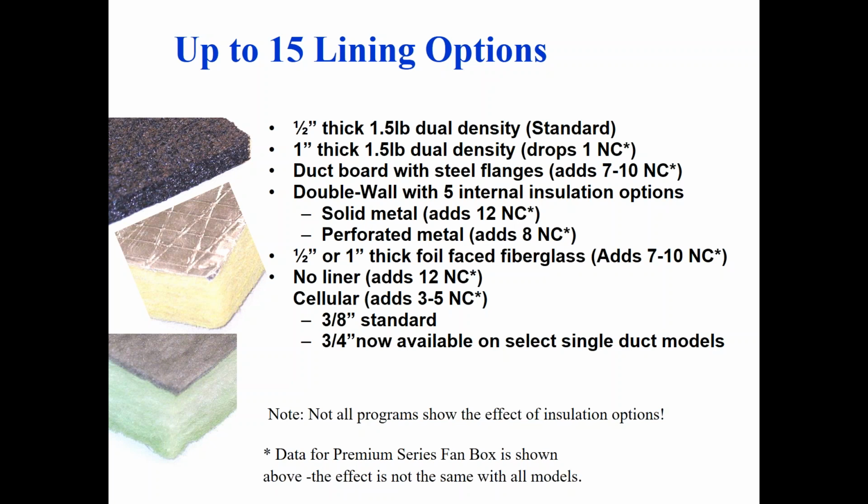Every liner option that you pick that is not the 1/2 inch standard one is going to be a sound penalty to you, with the possible exception of the 1 inch fiberglass liner. Most of the manufacturers don't even publish a difference in the sound on those two. It's immeasurable. But I'm saying here, maybe about 1 NC difference, because you have a thicker liner, but it's not even really a measurable amount. All of the other liner options are going to have a harder surface on them than the fiberglass will, so they're going to reflect sound, which is going to make them noisier.